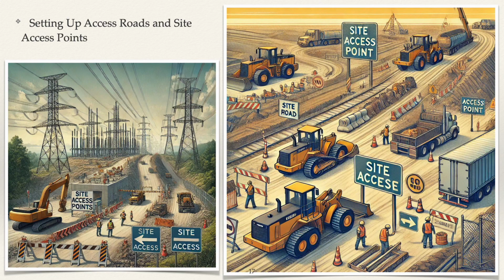Maintenance of access roads. Schedule regular maintenance for access roads to ensure they remain passable throughout the project. This may include filling potholes, grading, and clearing debris. Regular maintenance reduces delays and ensures safe conditions for vehicles.